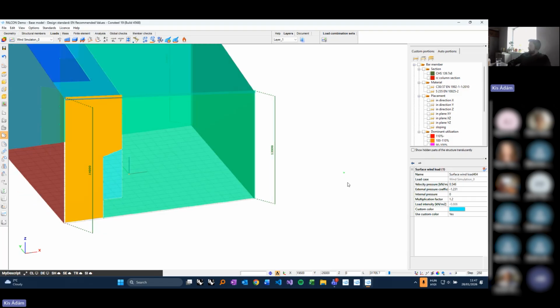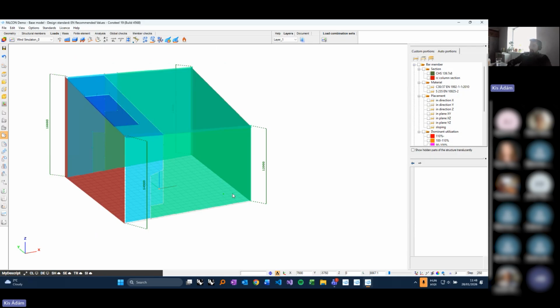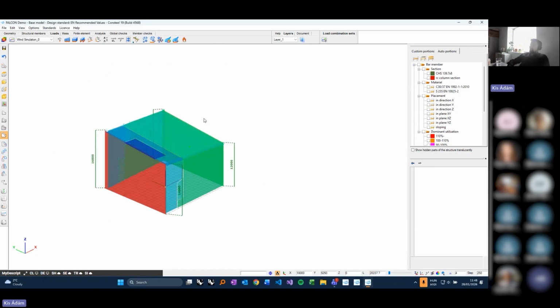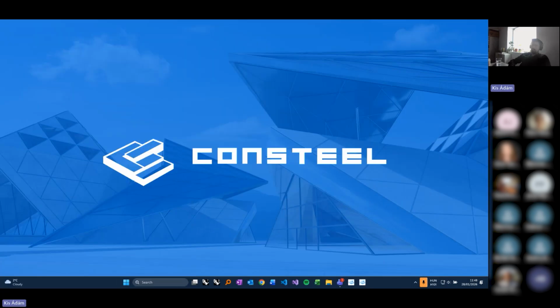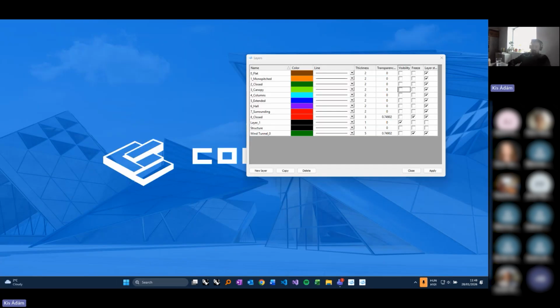And if you select a specific load, as I mentioned previously, these are actual surface wind loads with a certain velocity pressure at the reference height, which is the top of the building or the top of the surface, and the specific external pressure coefficient, which is minus 1.2, pretty close to the A zone of the Eurocode. Anyway, this was obviously the simplest scenario. Let me show a bit more complex case and explain in a bit more detail the simulation procedure itself.